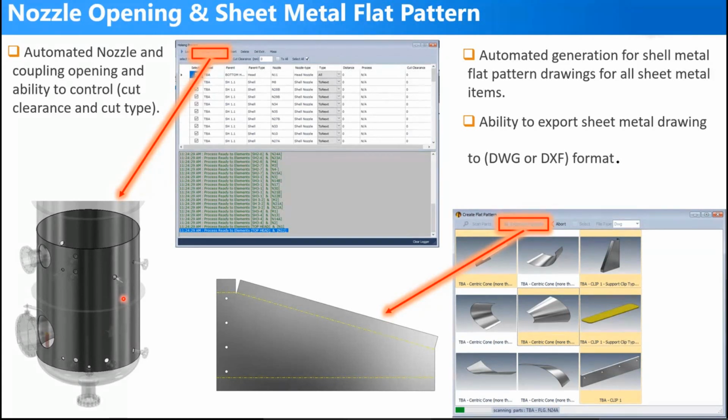Actually, from my side, as I know, we do the cutting after rolling. Because I am a static equipment senior design engineer, I have more than 14 years of experience in this field. As I have watched in manufacturing, we make the rolling. After that, after the rolling, we make the cut by using the sheet metal flat pattern. Okay, we will indicate the opening locations. After that, make a cut after rolling.